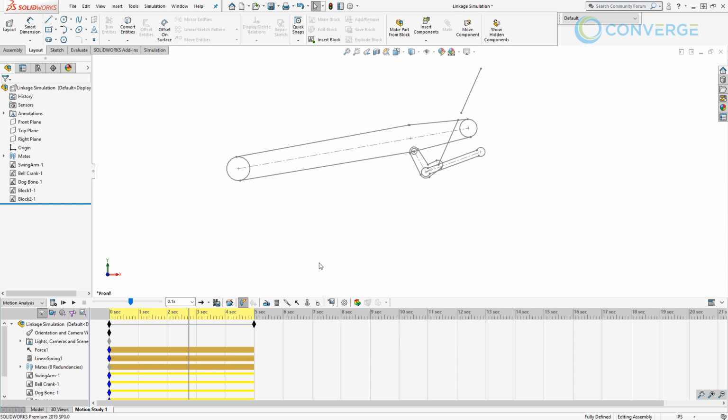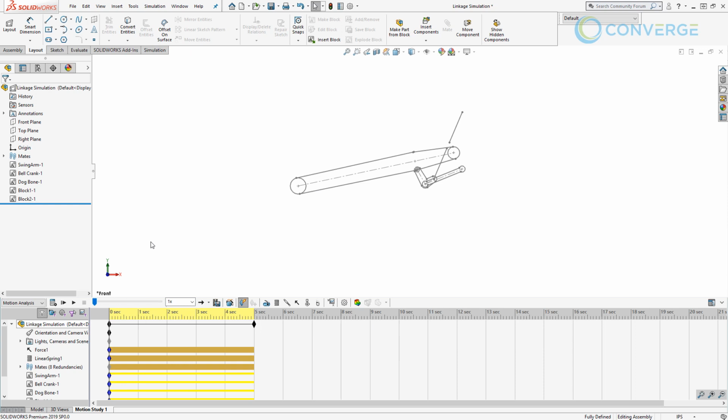So at this point in time, I hope you guys see that there is a lot of benefit to using sketch blocks for many different things. We've talked about using, again, sketch blocks for just the basic stuff, just creating them, making blocks, reutilizing them for things like bolt patterns. But then the kinematics aspect of it inside of SOLIDWORKS, ultimately going all the way down to the kinematics inside of the assembly.